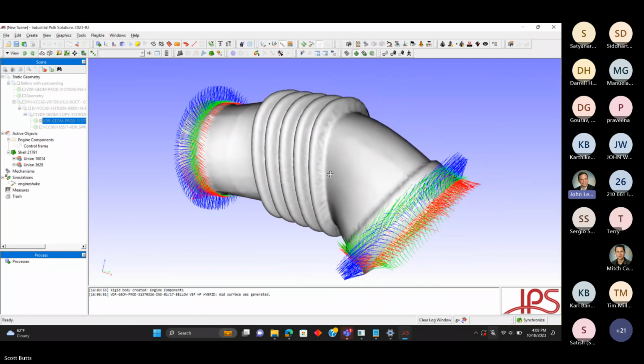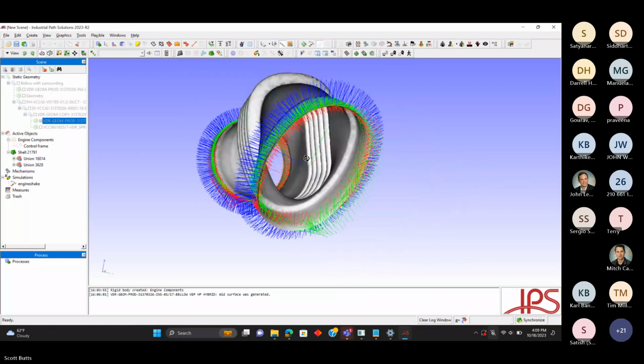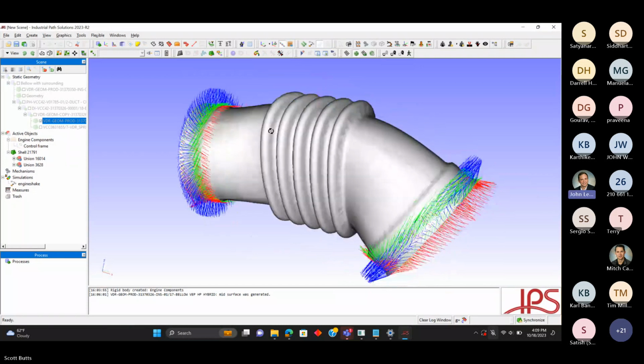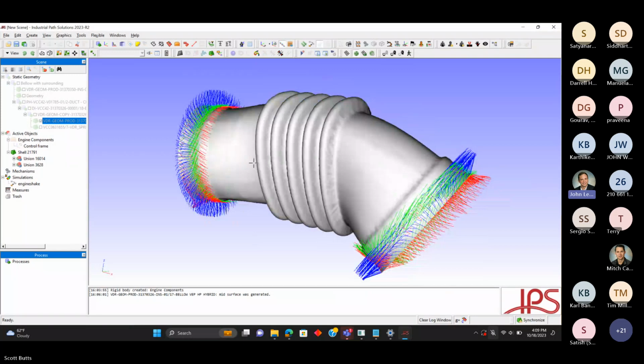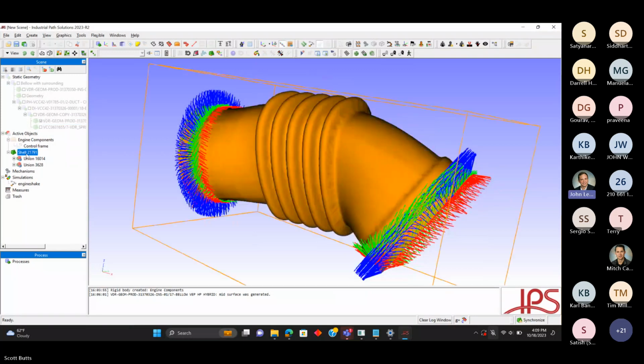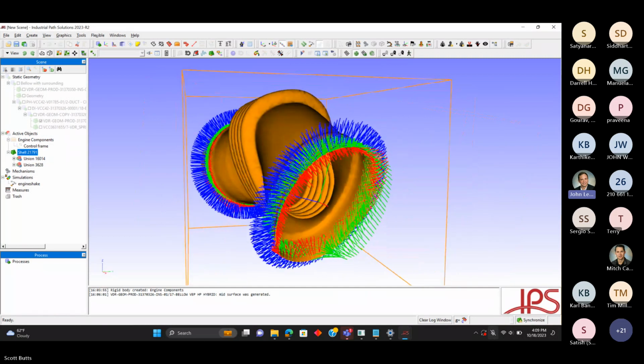So right here, this is the bellow we've generated. And you can see it does look a little bit different. That's because this is a middle surface, we call it. So we have the shell over here now in our object tree. And the shell, what that's doing is it's across the mesh, it's kind of finding the average thickness, and it'll go right in the center of that.